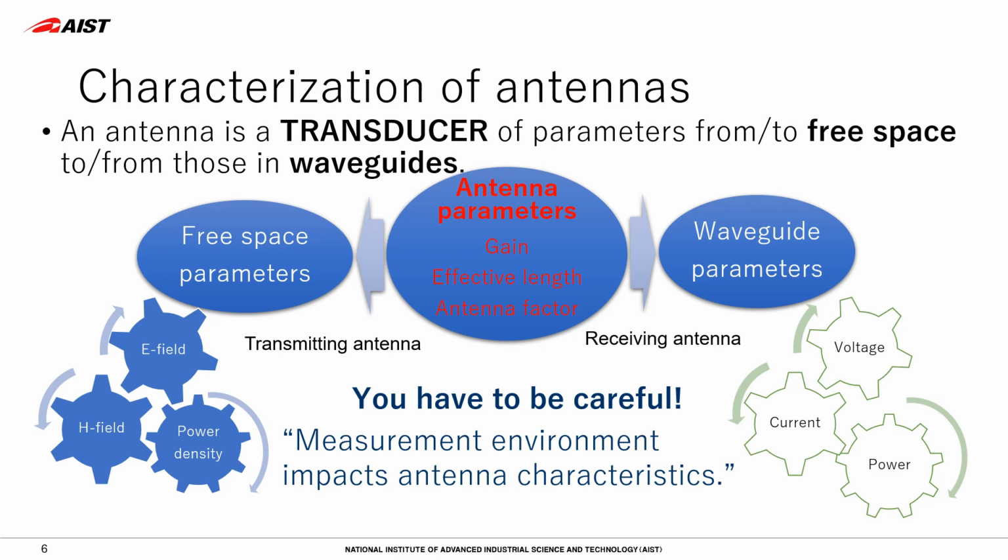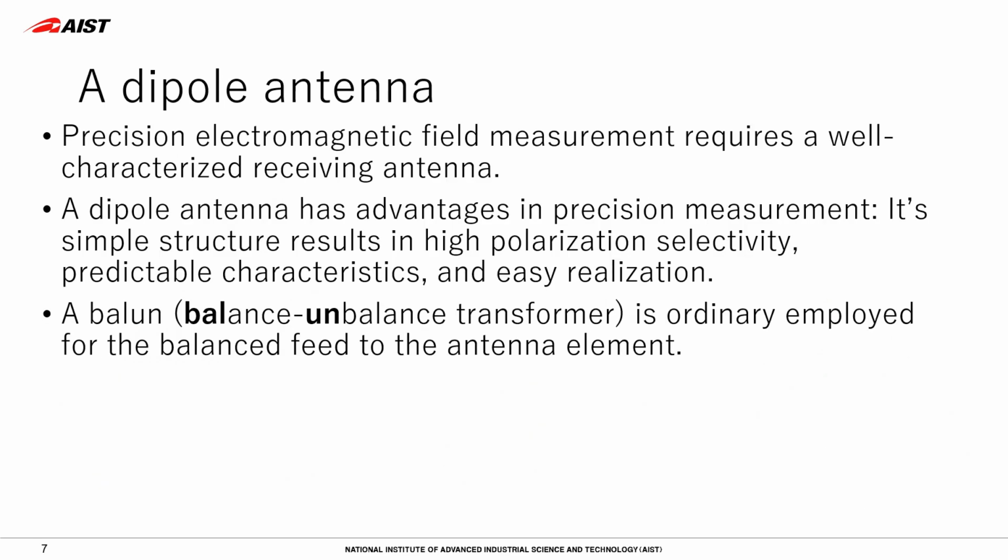One more thing that you have to keep in mind is that your antenna couples with the surrounding environment when you use it, and the antenna characteristics may not remain the same as the calibrated ones any longer. You may have a big number of antenna options, since antennas have been developed to fit the application purpose, like mobile communication and radar. So we should select a suitable antenna type for the measurement purpose.